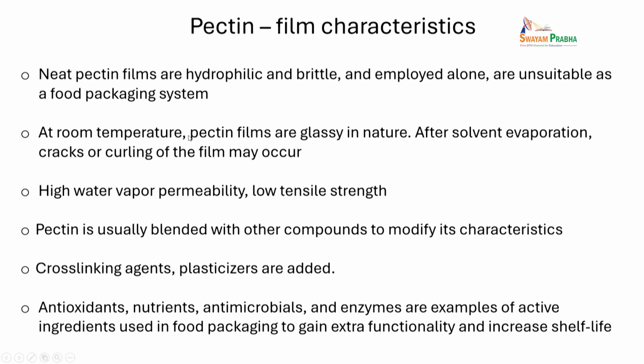Now, if you consider just the neat pectin, the virgin pectin alone, you will see that these pectin films are quite hydrophilic, and they are quite brittle. They are easy to tear if you use them alone. Therefore, they are not really suitable for a packaging application. If you leave a pectin film on the table, after some time it will absorb a lot of moisture and become very sticky. So that is one issue with native pectin.